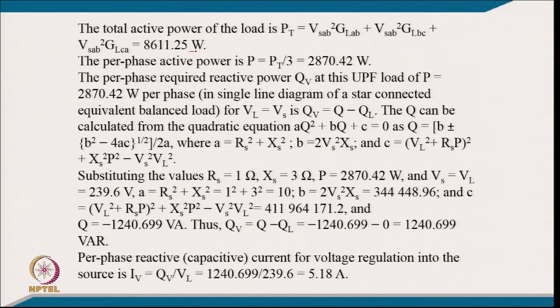So, it comes to 8611.25 watt, and per phase active power will be divided by 3. So, it will be 2870.42 watt, and per phase required reactive power for voltage regulation at this UPF load, P equal to 2870.42 per phase.